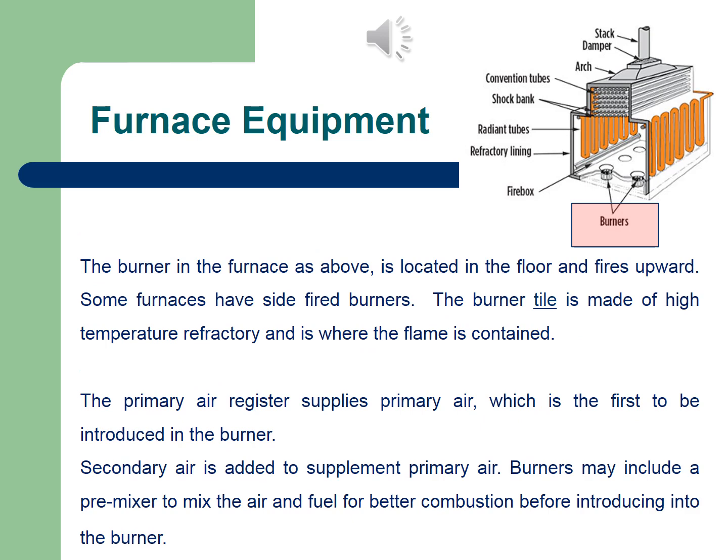Okay, and so we're moving to the last equipment associated with the furnace. I would say the most important equipment, and this is then of course the burners. So if we look at the burners, looking at the picture above, usually it's located on the floor and the fires are fired upward. Some of the furnaces have side-fired burners, depending on the design. And then also another important aspect is the burner tiles, made of high temperature refractory, which is where the flame is contained.